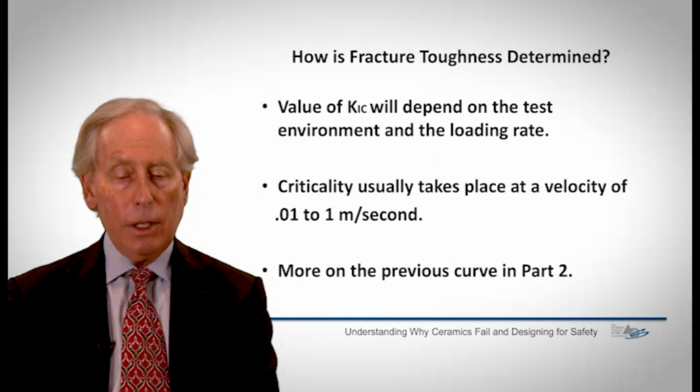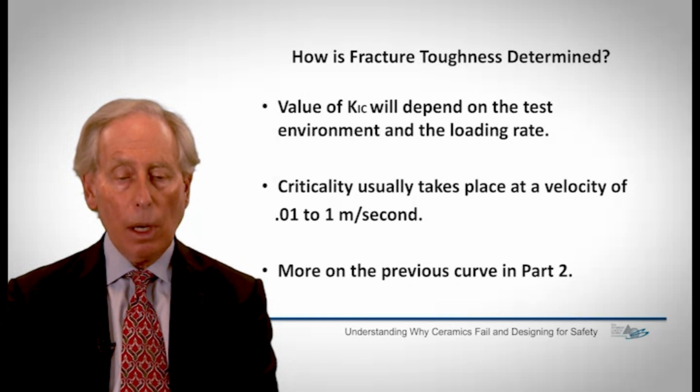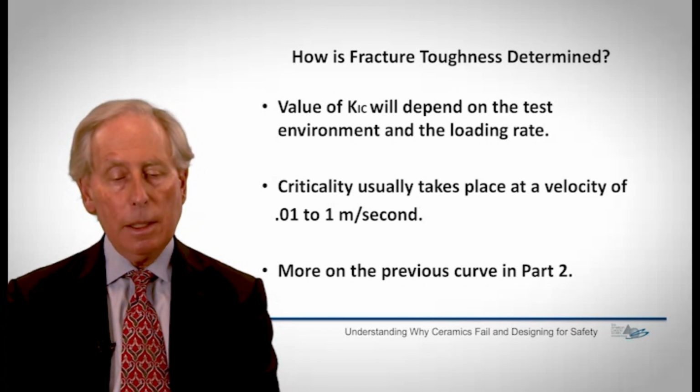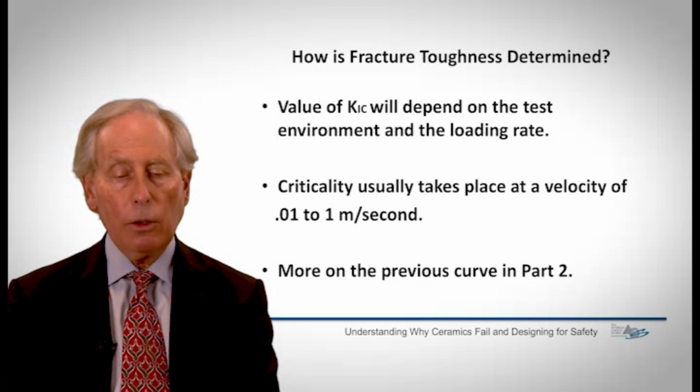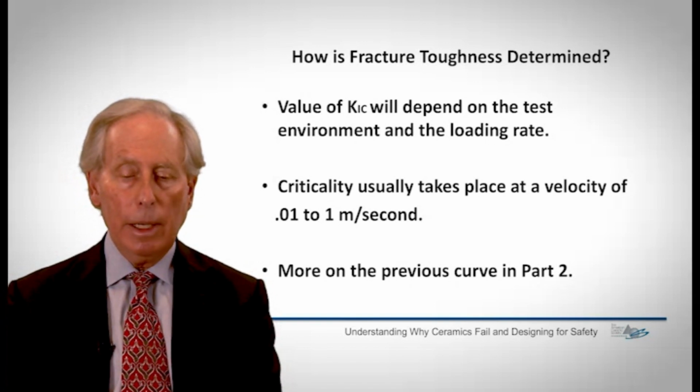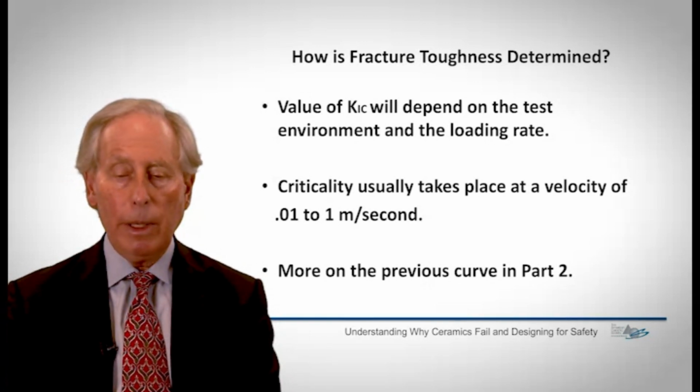So again, just reiterating some of the things I've already said, the value of that fracture toughness number will depend on the test environment, will depend on the loading rate, and as I just said, it's something between 1/100th of a meter per second and 1 meter per second where criticality occurs. And I'll say a lot more about these kind of curves in part 2 when I talk about environmentally enhanced crack growth.